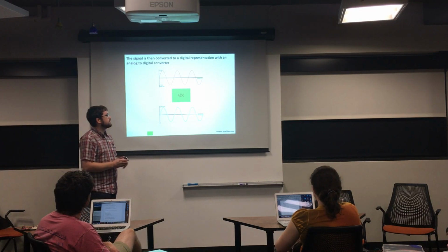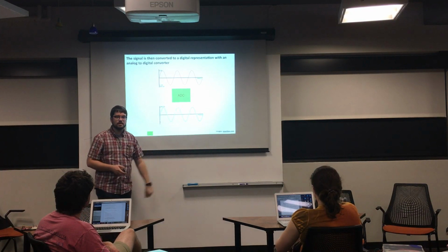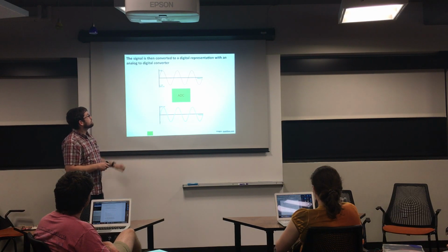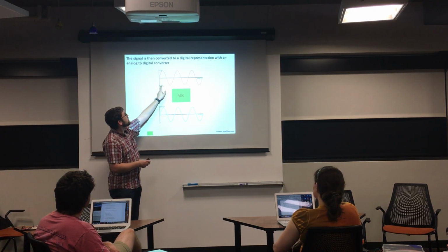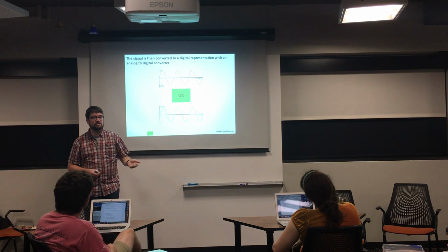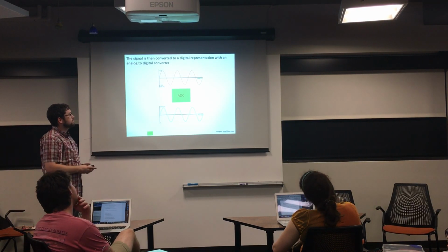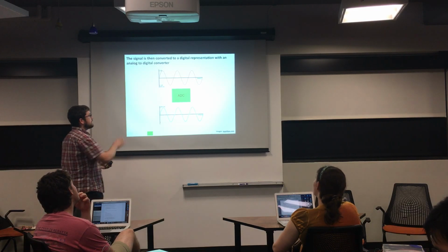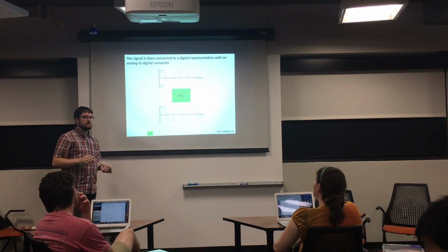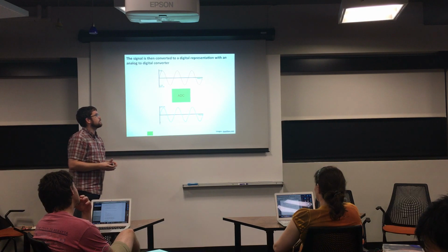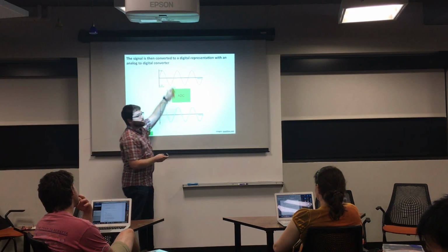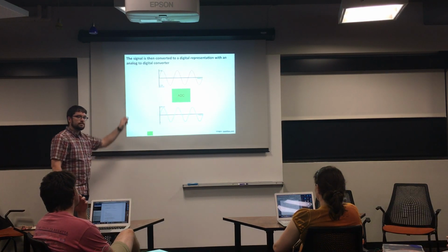But for now, we're going to say there's a box, in this case a green box on a black box, called an ADC. So if you have a signal, let's say we're looking at a sine wave up here, this could be like the power that's coming out of the wall, and it's plus or minus 120 volts in this case. It is a continuous thing in time and in voltage, right? So we can't get from 0 to 120 volts without going through every voltage value.